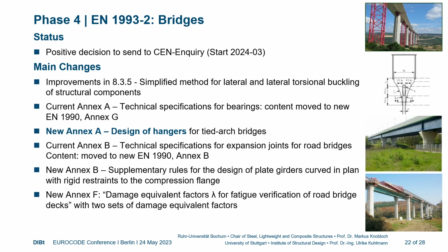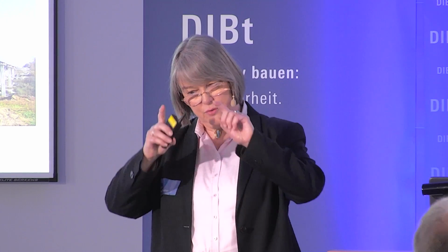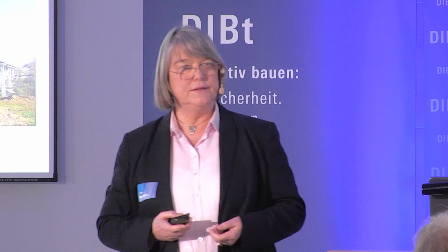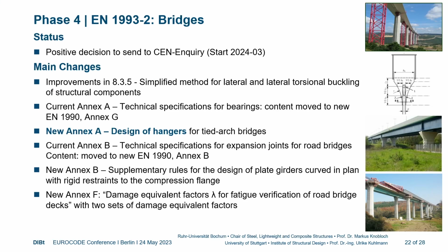We have a new Annex A dealing with design of hangers for tied arch bridges, and perhaps this is a bit of a special feature, because by fulfilling construction rules, you succeed as user in avoidance of vibration of these slim elements, but also you do at the same time fatigue verification. So this is a very useful scheme for that.